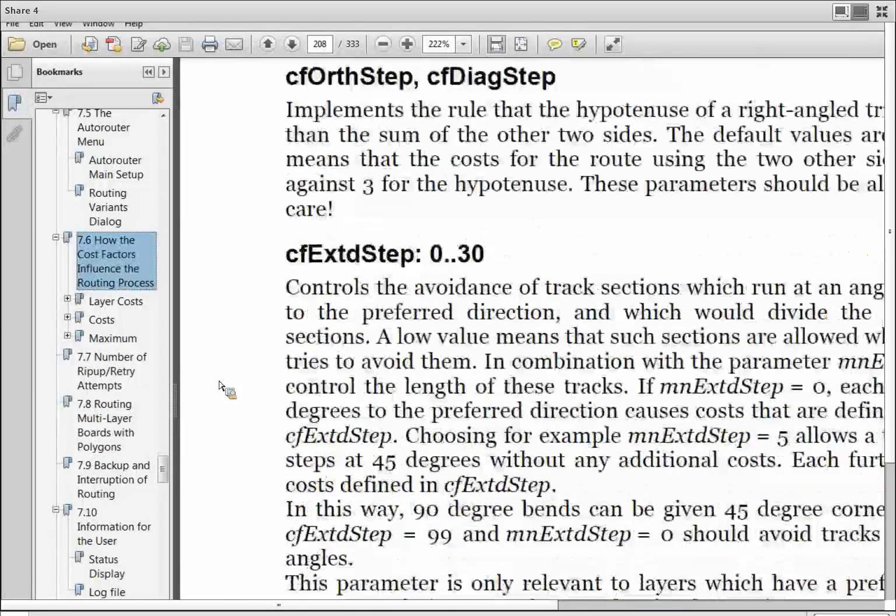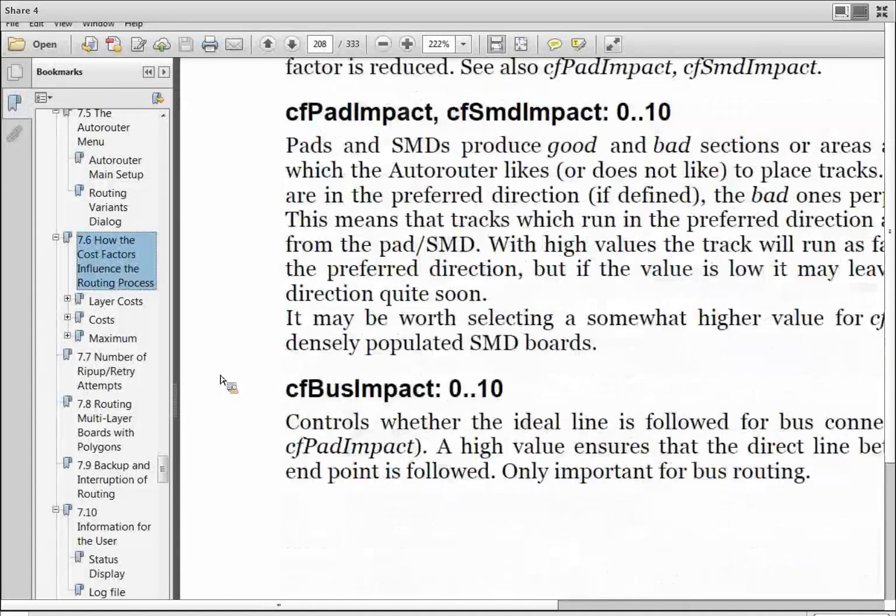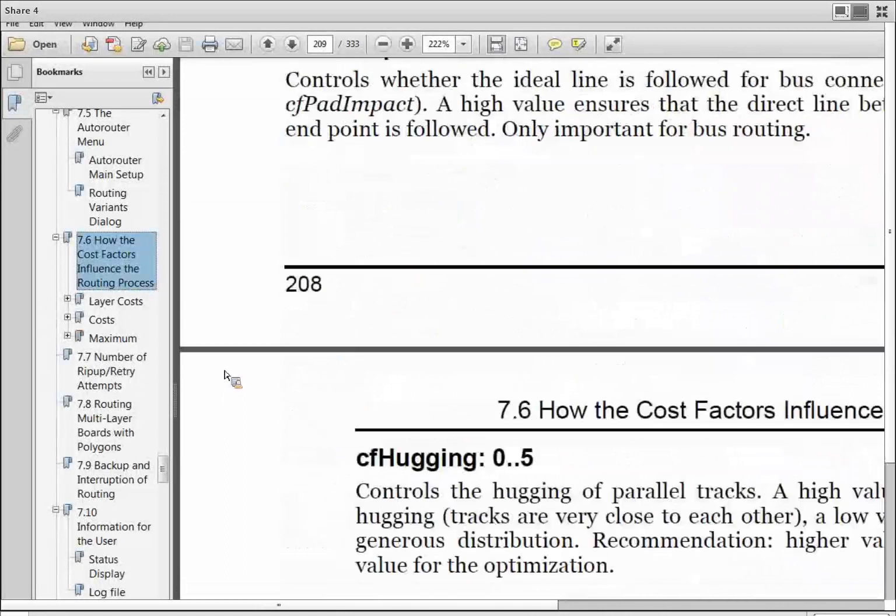Okay, in the case of that topological router algorithm that I mentioned previously, I mentioned that it's auxiliary. So it's not a complete replacement of the old algorithm. So this information is still valuable when talking about the top router. What the top router does is that it analyzes the board and produces a rough sketch of best paths, and then gives it to our old algorithm to use as a guide when routing.